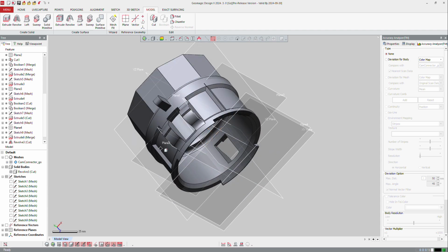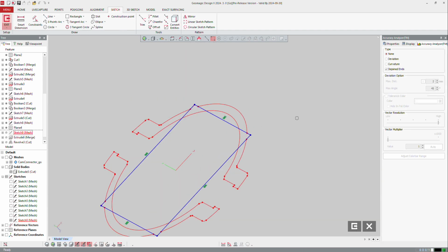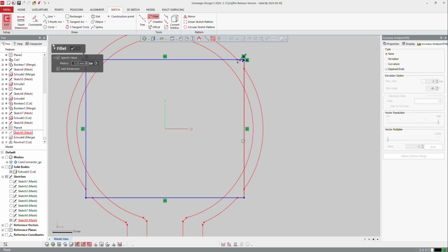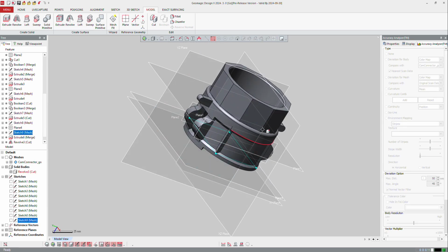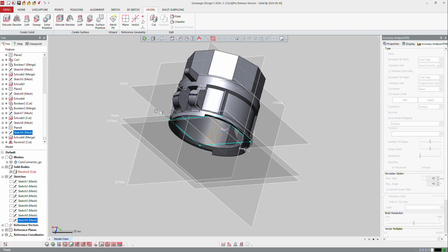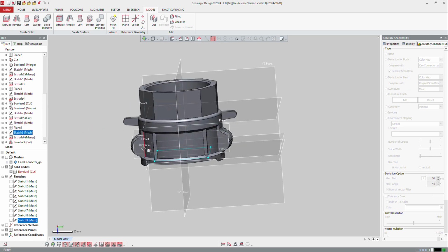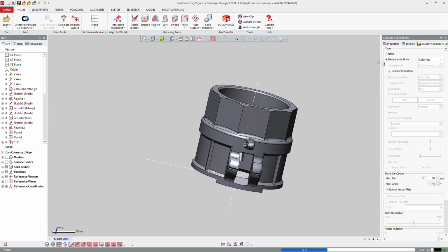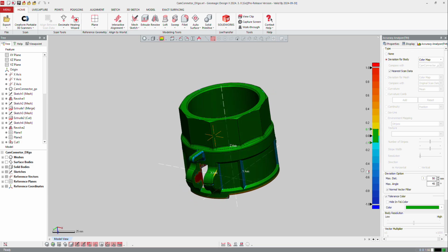And again, I can still go back to this sketch and say, well, okay, but those squares, I need to make a little fillet of 0.1, so specify a value of, well, 0.25. And let's see how it does here. 0.25 here, 0.25 there, and go on the rest of the part. And okay, and everything again is updated on the part, and you have a nice definition of your connector. And here I just created some fillets and added some extra material. And again, at the end, always go to the deviation from body, and you can see that it's quite accurate.